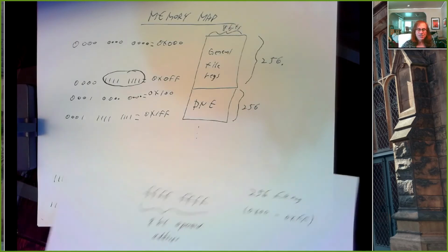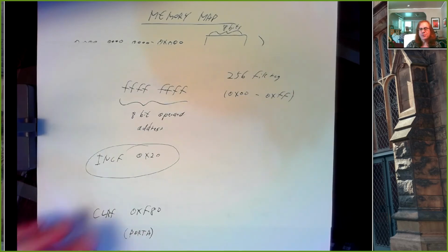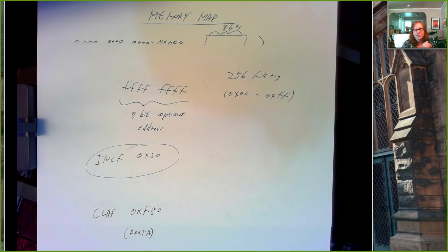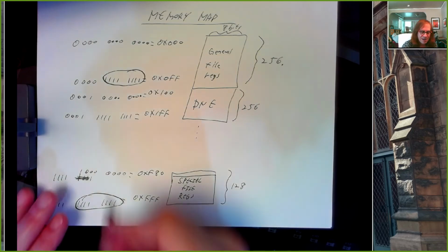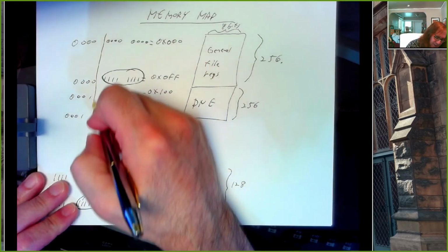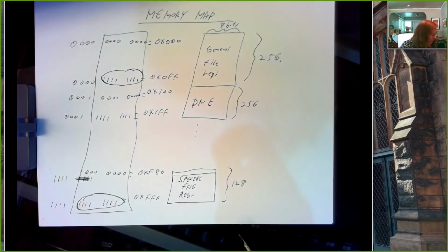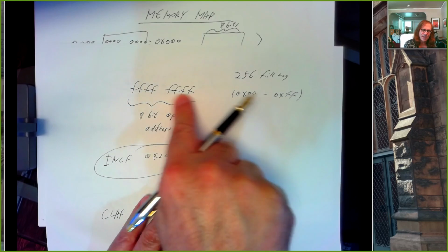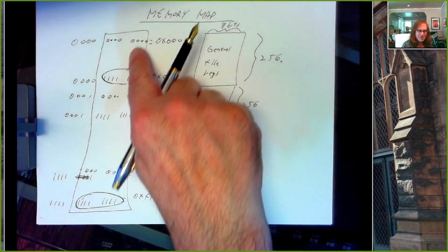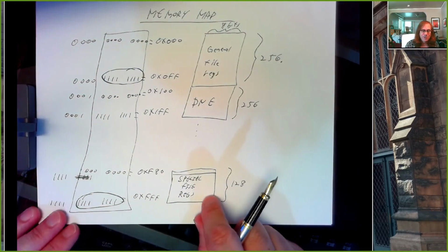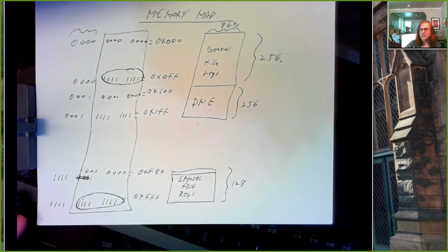So the access bit is a shortcut, because really we need 12 bits to specify an operand, and we don't have enough space to specify 12 bits. So here's what we do. We specify as the operand these lowest 8 bits. That's the 8 Fs in the pattern for an instruction. We specify these as part of the instruction's binary coding. But then we use a trick to specify what these upper 4 bits are.